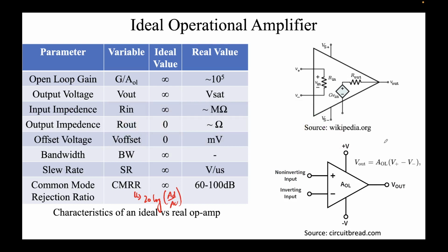By V, which value are you talking about? I'm talking about V out here. V out is dependent on R out, because a current will be flowing here. If you connect some load, there will be some current flowing through this, depending on the direction, so there might be some drop. It's not that V out is completely independent of R out. It depends on the current flowing. But in the ideal case, if we take R out equal to 0, whatever the amplification is, that whole amplification will be reflected at the output node here. There will be no loss inside the circuitry of the op amp itself, to put it very crudely.